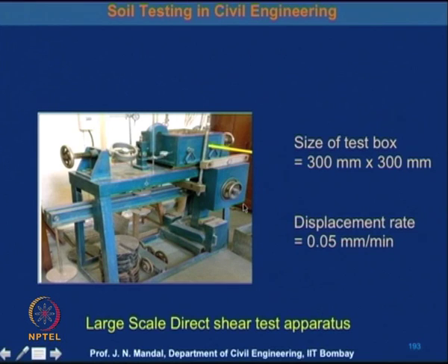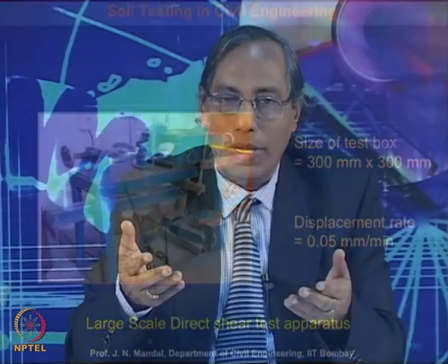When the soil sample has larger size aggregate, you have to perform the test using the large scale direct shear box test. Or if you want to test geogrid or geotextile material, it is always recommended to use the large scale direct shear test instead of the small scale direct shear test, so you can have the appropriate result.